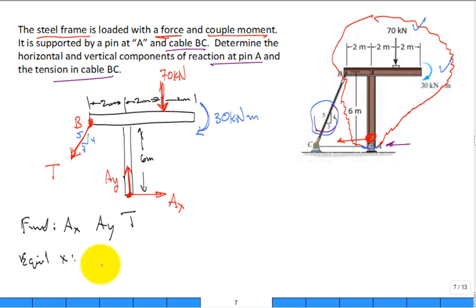Let's write it like this. AX is completely in the positive X direction, and we're going to have the tension, but it's in the negative X direction, and I pick off that component using that similar triangle, I pick off 3/5 T, negative 3/5 T. So I have two things on this object to make it want to translate in the x direction.